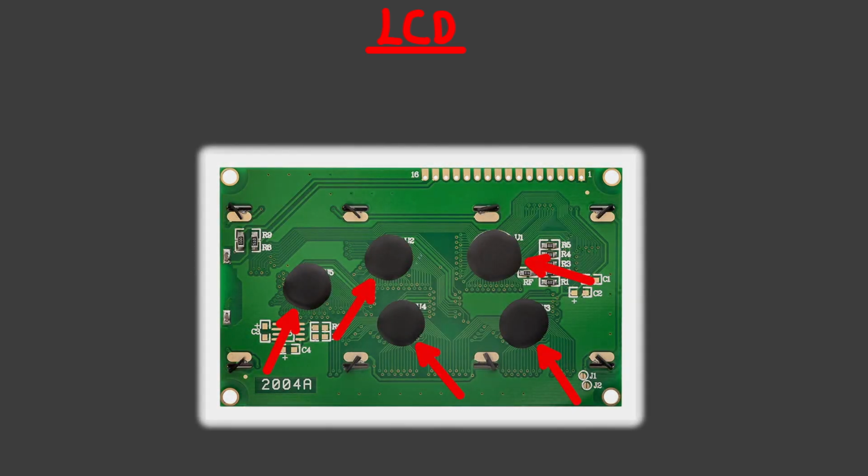Some of the sellers won't tell you the driver chip, and you can't really see it from the construction of the LCD either, since they use black epoxy to cover the chip. But all 2x16 and 4x20 LCDs I have on hand work without a problem, so as long as you buy one of those, or similar, it should be fine.